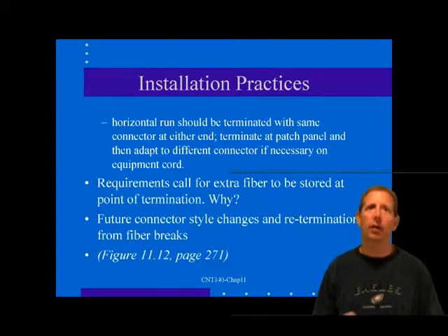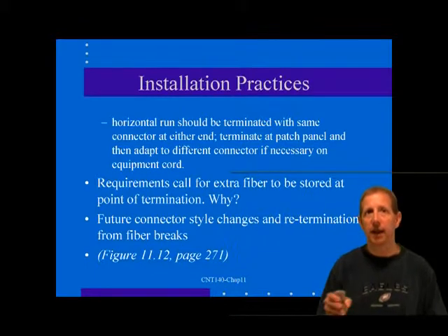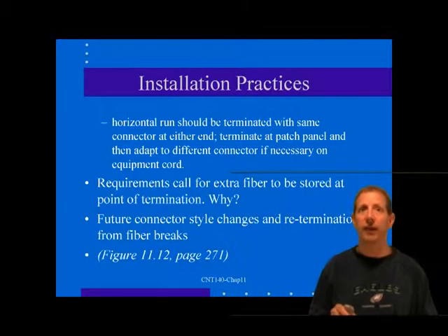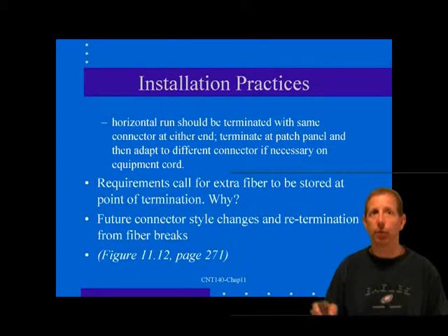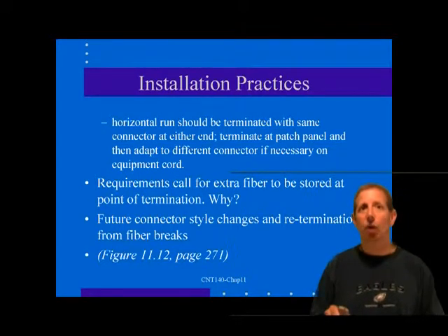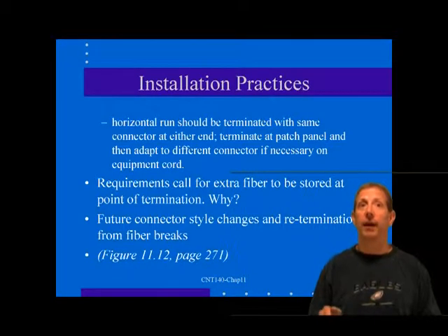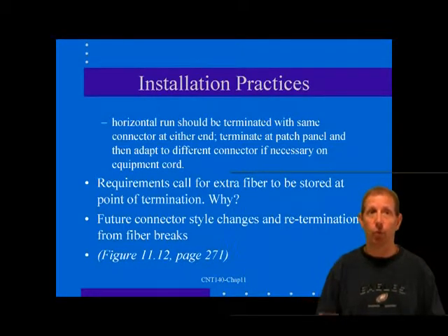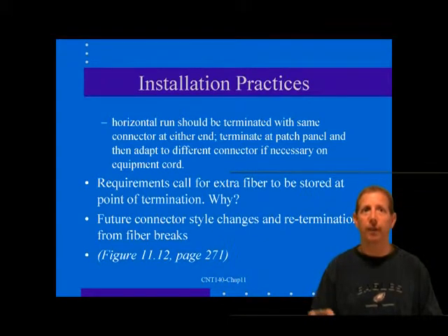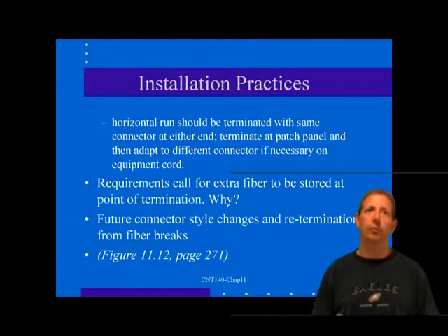The buffer coated fiber or fibers must now be prepared. The tight buffer is removed with a tool that is essentially a wire stripper. The buffer stripping tool is often a fixed opening tool that is specifically designed for the diameter of the bare fiber core and cladding, so that the fiber is not nicked when the buffer is removed.